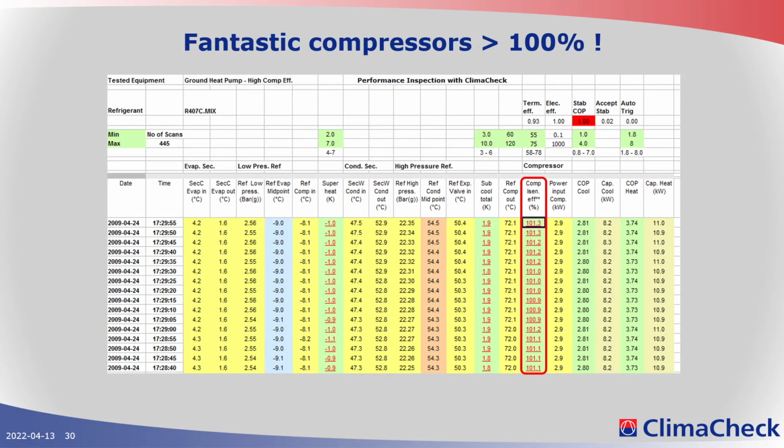This is a really fantastic compressor. We have over 100% isentropic efficiency of the compressor. Of course we do not. So I don't want to hear about these compressors, because anybody can understand that we don't have such compressors. I've told you that they are never more than 75%. And if we have 100%, we are doing something wrong.